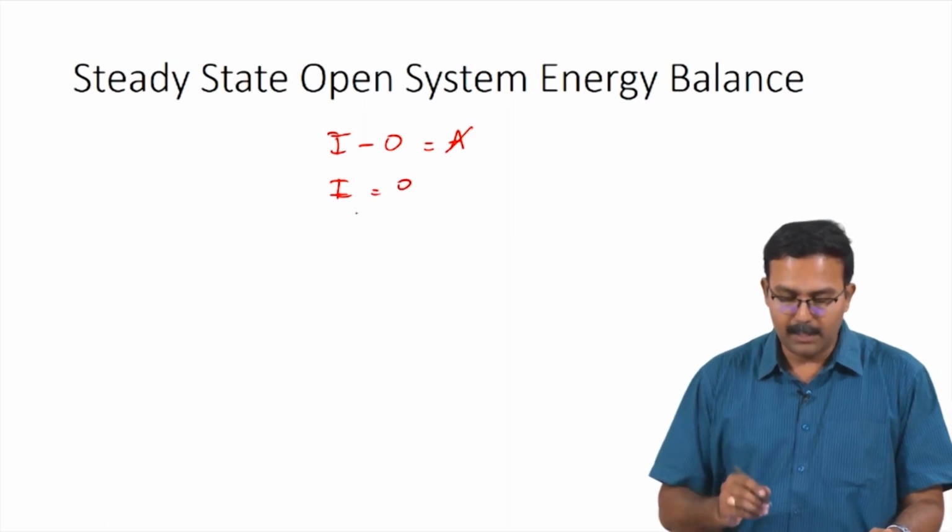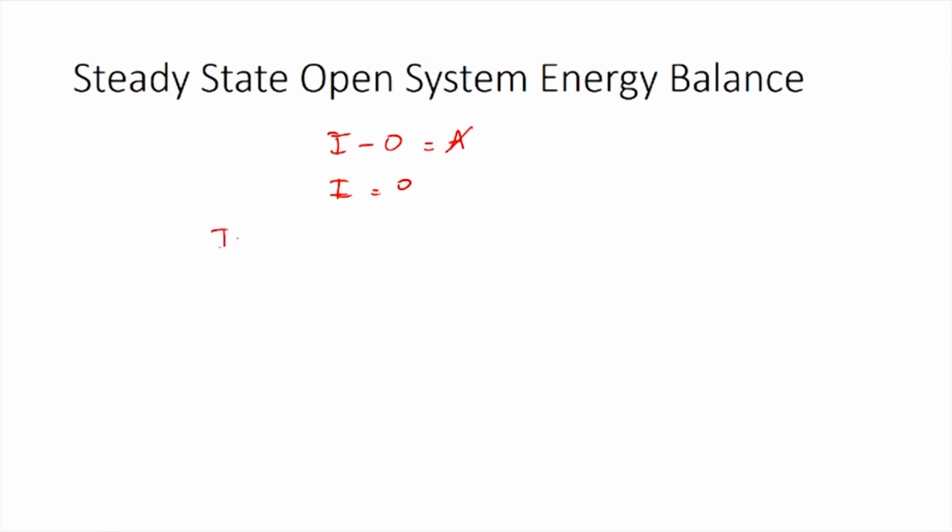So, let us start writing the balance equations for this. Energy which is fed to the system, the input, would be sigma of input of Ej dot, where E is the total energy possessed by a component j, and the summation of all the energies of different components will give you the total energy of the input stream. In addition to this, you would also have Q dot, which is the heat which is supplied to the system. So, this would be a positive term.